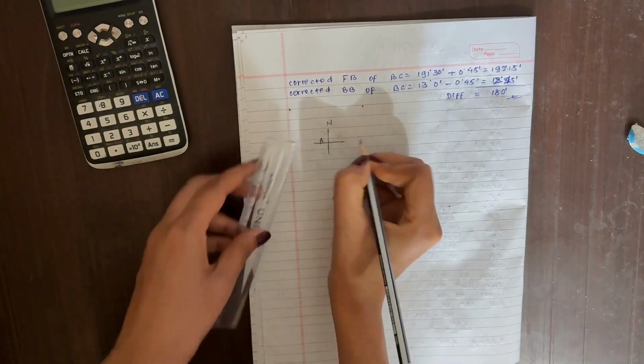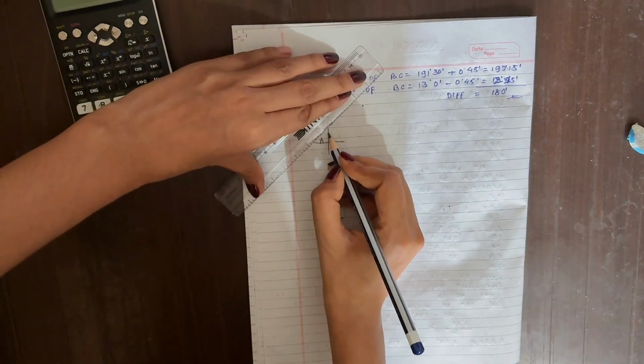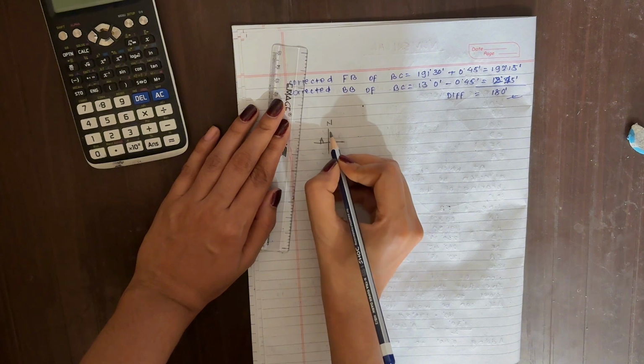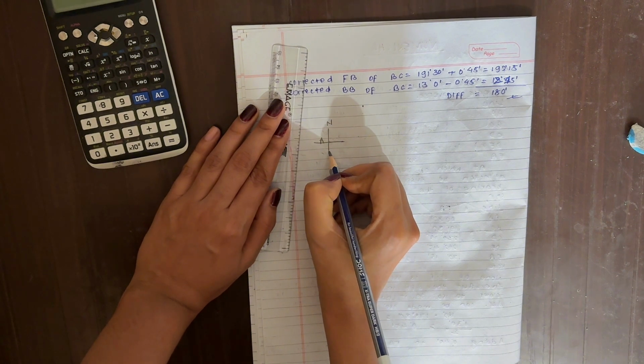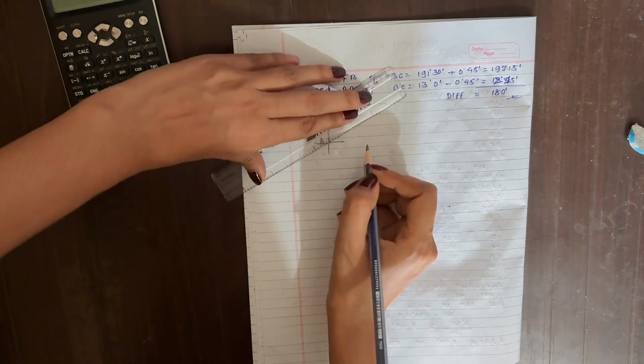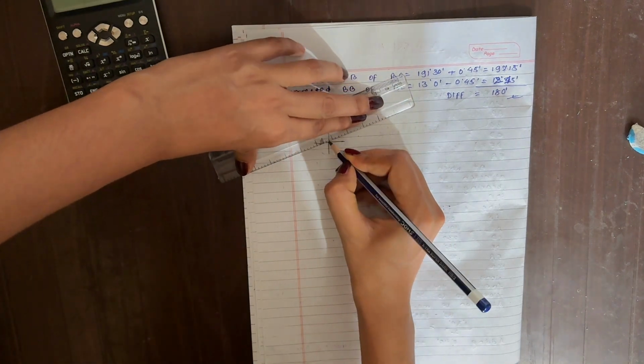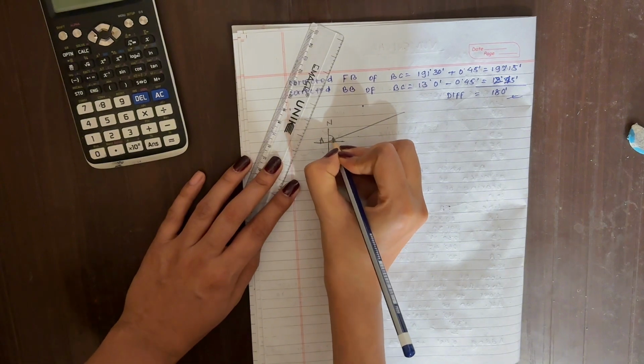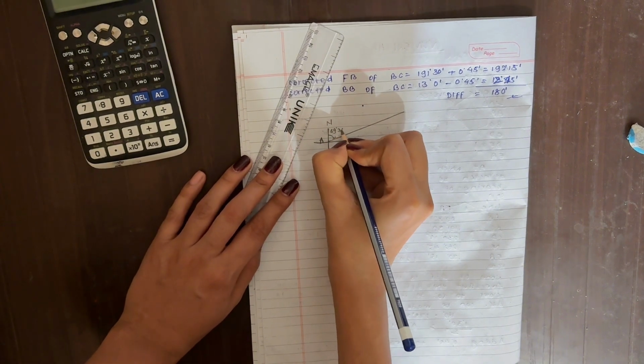This is station A, and we measure from the north. So it goes from 0 degree up to 90 degree, then up to 180 degree, this is 270 degree, and the round completes at 360 degree here. So 69 degree must be here. This is just a rough sketch. This is 69 degree 30 minute.